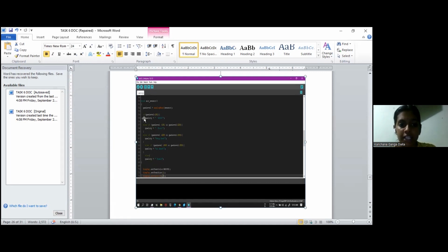After that, we can use it like this: if it is less than 181, you display good. Else if it is greater than 181, you display poor. If it is greater than 225, you display very bad. If it is greater than 300, you display you are dead. And if it does not fall in any of these values, it will display false. So this is an example idea. In this way only, we will write a code for the Arduino.